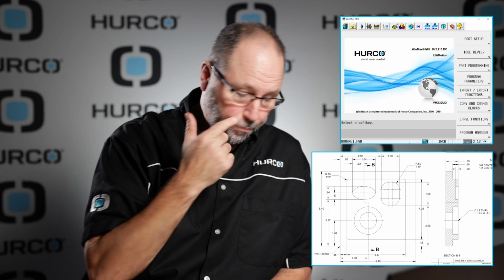All right, we're going to do Intro 5 print out of the packet today. This is the first time we've done more than one type of feature together to put together an actual part. We're going to have different features on this part. We have a mill frame that goes around the outside, a counterbore and a circle through the middle, and an ellipse, which we haven't talked about yet. We'll do the ellipse block first, and then a mill frame that actually goes through the entire part.